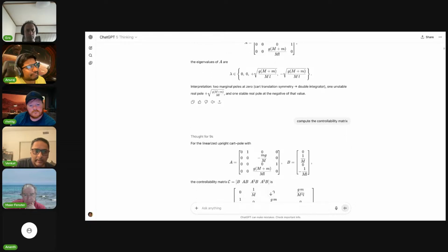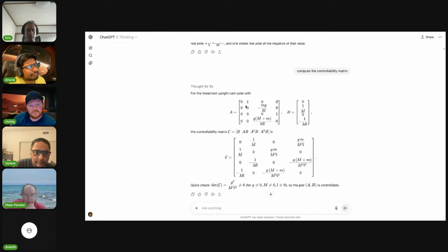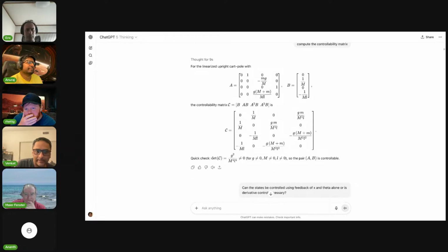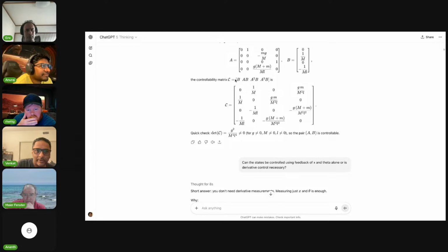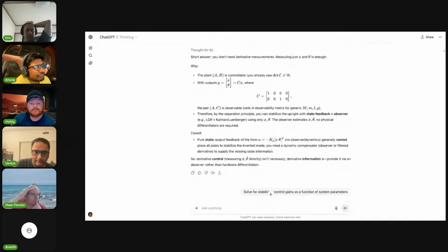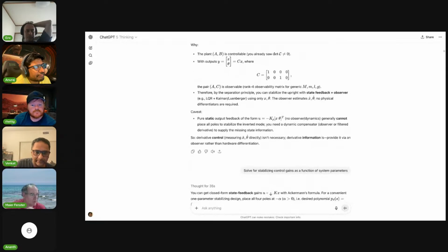So let's see, what else can we say? The typical first thing you want to do is ask if the system is controllable at all. And again, I'm just flashing this at you. You compute this thing called the controllability matrix, which is, multiply the matrices in this order. And then you check the rank of this matrix. If it's full rank, the system is controllable. So these are some technical things you do. Again, just basic awareness. It's also observable in this case, trivially.